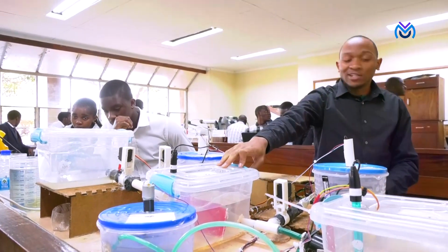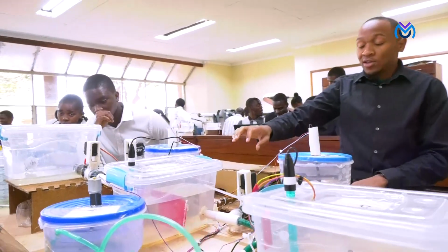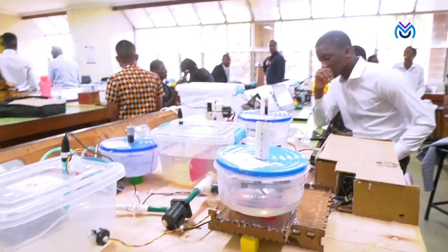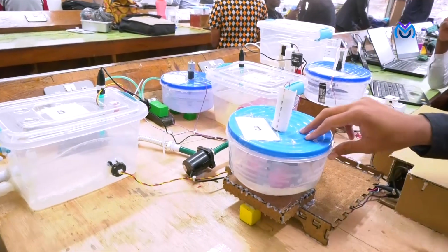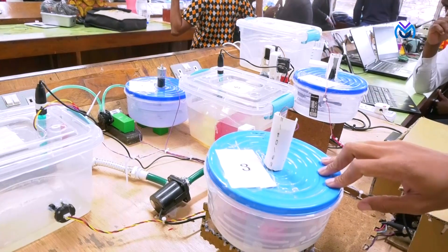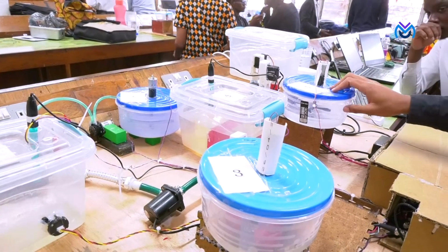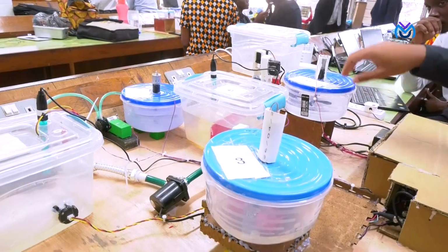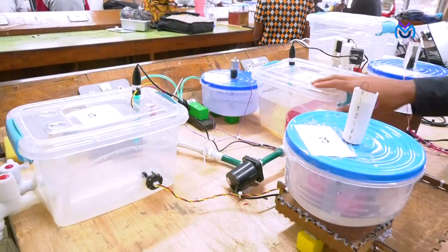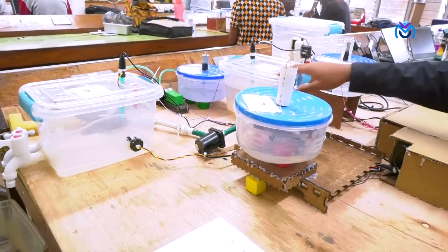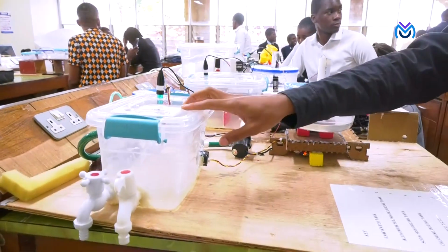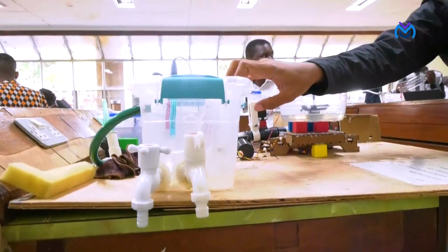The next tank, tank number 6, is the sedimentation tank, where flocculation occurs when the coagulant mixes. Tank number 3 is a soda ash tank, which corrects the pH after the aluminum sulfate is dosed. In tank number 4, we have chlorine, which removes microorganisms after we have dosed these 2 chemicals. The 5th tank is the clear water tank, which collects treated water.